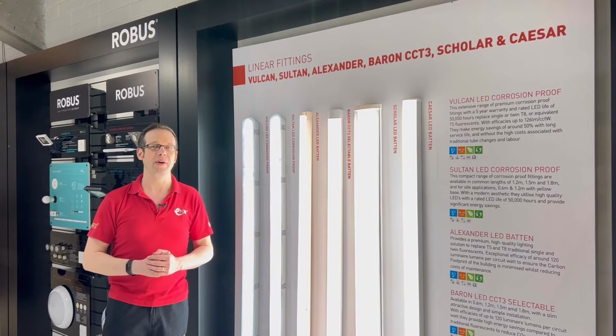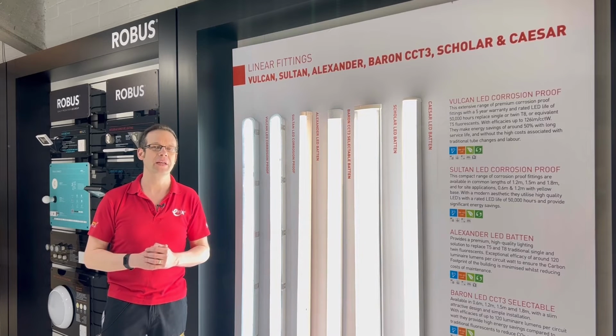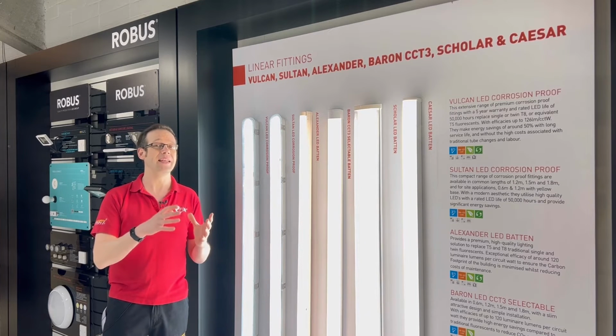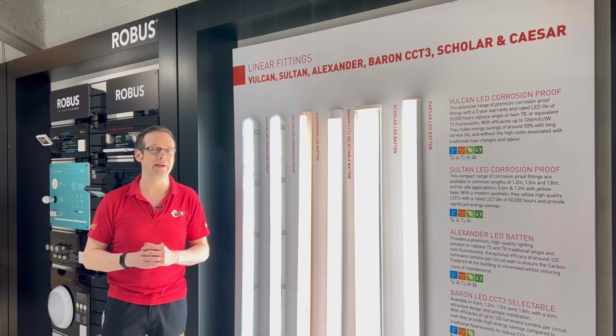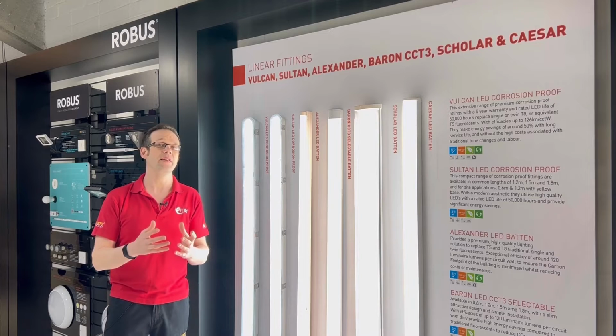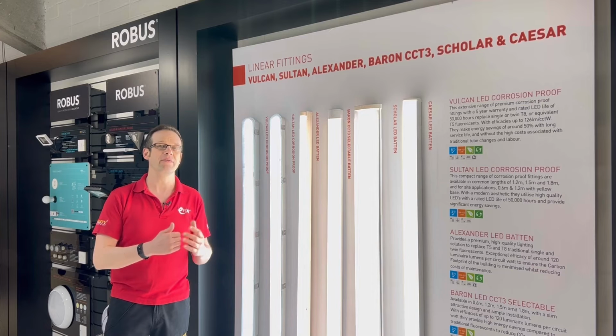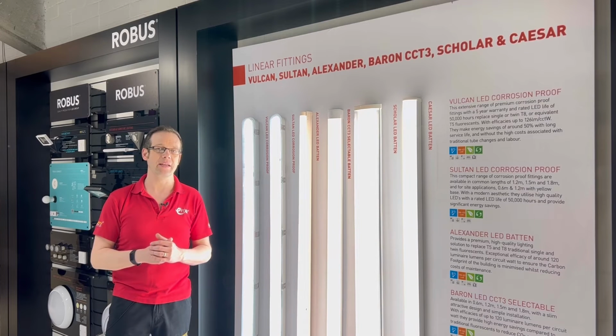These are environments where the light fittings need to be a little more robust in terms of resistance to mechanical damage, but also to the ingress of moisture and even fending off attack by atmospheric chemicals. So to install linear lighting in areas like this will require the use of a sturdier type of fitting, often referred to as a corrosion-proof fitting, which is generally made of a tough plastic body which will prevent corrosion at the hands of moisture and airborne pollutants, and they also generally have higher IP ratings to prevent the ingress of moisture to the inside of the fittings.